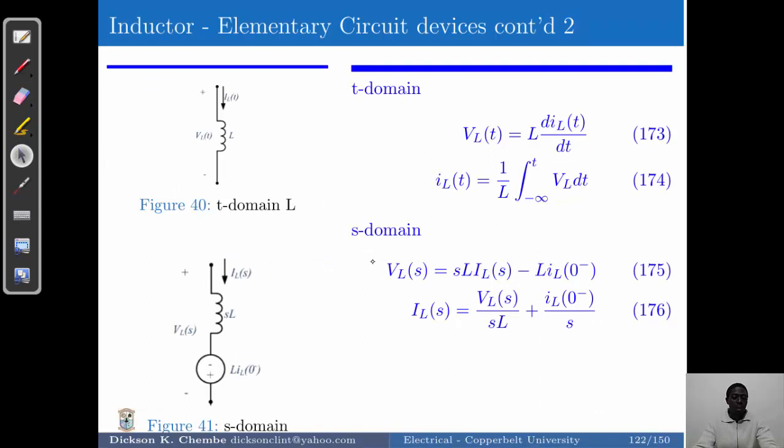And so a comparison of the calculations then follows. If we look at the time domain, we've got the voltage source value shown in this way, and we can get the current value iL(t) to be solved from 1 over L times the integral of vL dt.